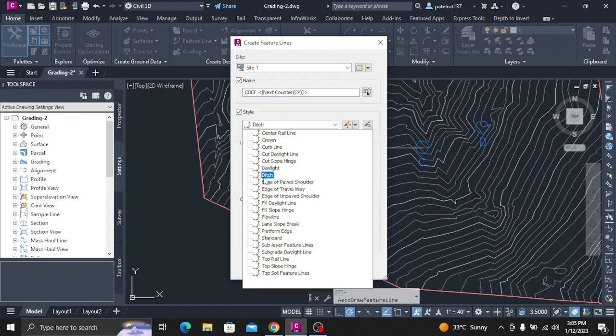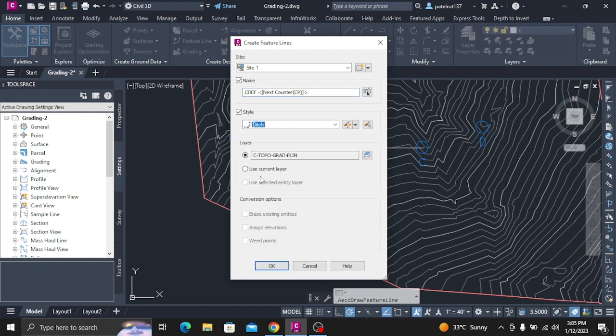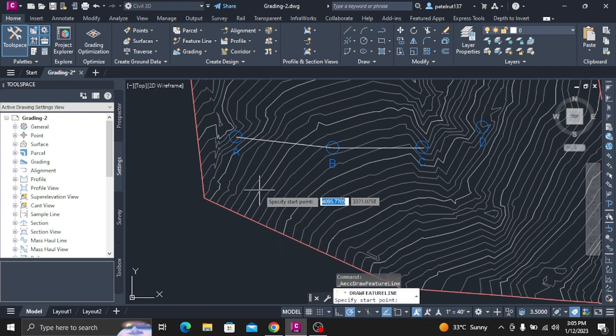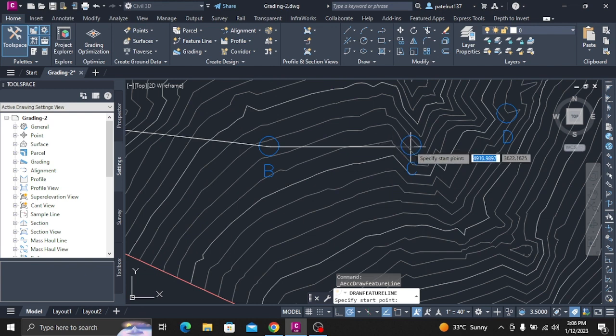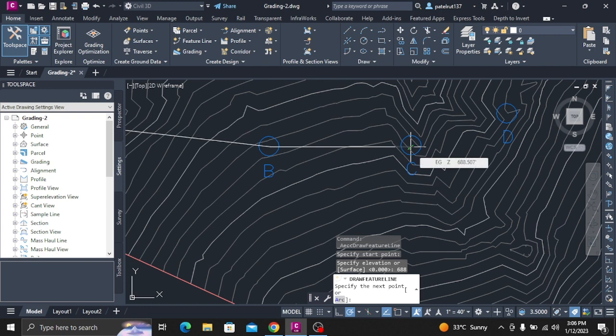Click Feature Line AB. Move the cursor over the surface near the elevation point to see the surface elevation displayed. In the Grading Elevation Editor, set the elevation point to an elevation that is at or below the surrounding surface. Drape a feature line on a surface. If necessary, press Escape once or twice to deselect feature line AB. Click Modify tab, Edit Elevations panel, Elevations from Surface.